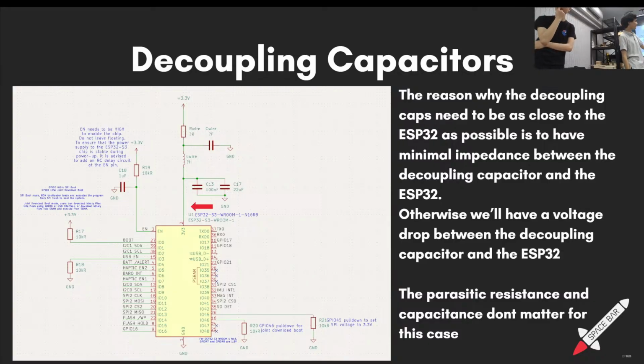So that I can deal with this small impedance, because it takes time for the power to get from here to here because of the inductance. So this is why we would have multiple decoupling capacitors. Okay. So this is probably by far the most common reason to use a capacitor in your digital circuits.